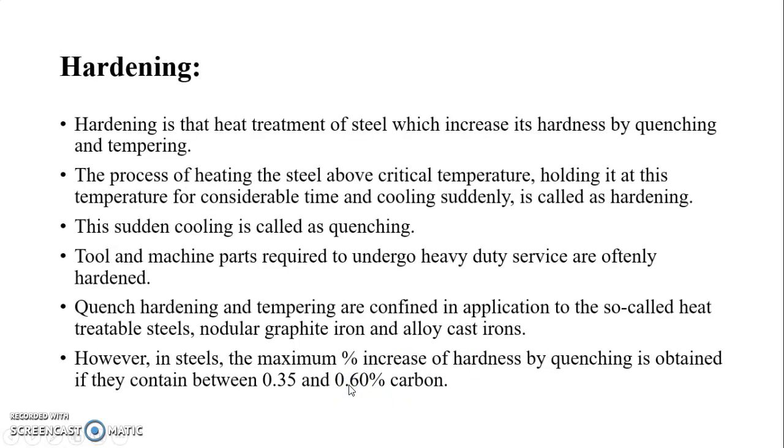Then the next topic, that is hardening. Hardening is that heat treatment of steel which increases its hardness by quenching and tempering. The process of heating the steel above critical temperature, then holding it at this temperature for considerable time and cooling suddenly is called hardening. This sudden cooling is called quenching.